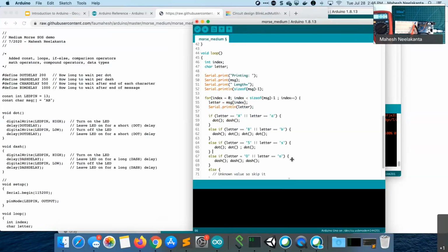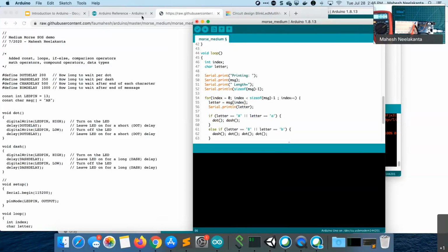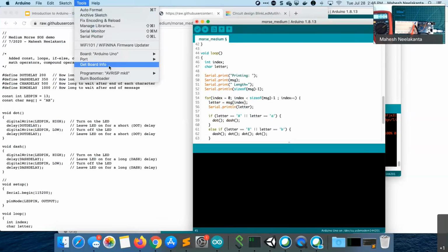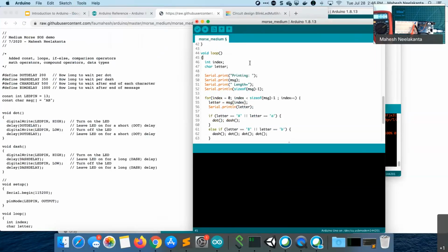So just a reminder, if I go to my Arduino and I go to tools and I can check my port, make sure, oh, if you notice, on my Mac, I don't see my port. And I'm actually going to do this so you can see an error. Remember that I turned off my Arduino? Well, I was pressing that button. Well, it's not connected. Watch what happens when I click upload.